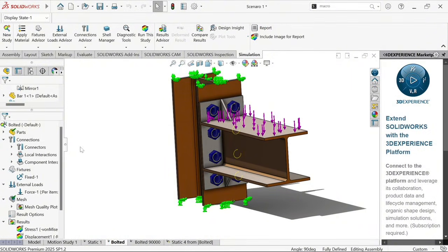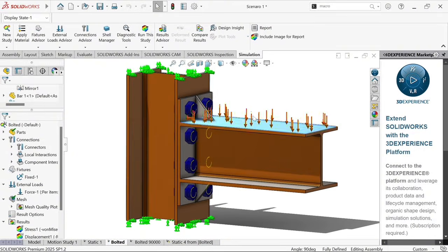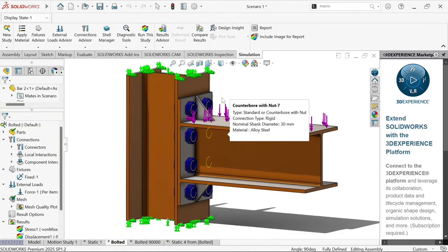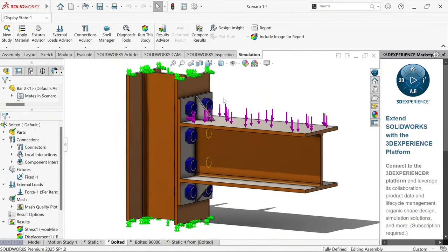Now, by default, when you import an assembly file into SolidWorks, it assumes the parts are bonded, and we don't want them to act as if they are from one carved part. We want it to show that we are bolting them together. That's very, very important.